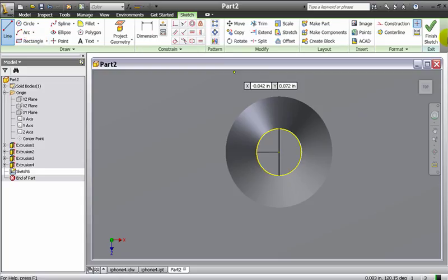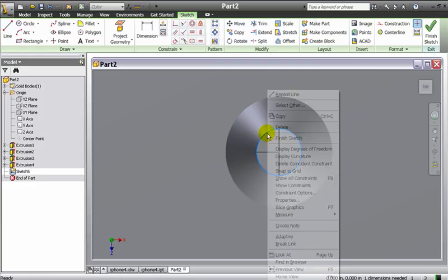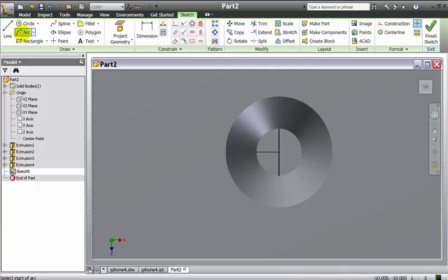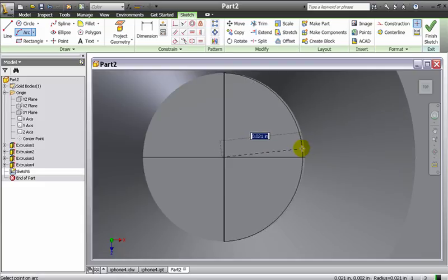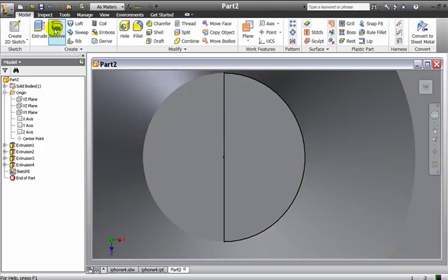Right click and go to done, delete this yellow line, and I'm going to grab my arc tool and lock onto the center of this line. So I'm grabbing my arc tool, locking onto the center of this line, and then follow it up to the top, click once, click on the other side, and then pull your arc out until it's lined up with this circle here, just on the edge here. So right there, click, go to finish sketch, and then click revolve.